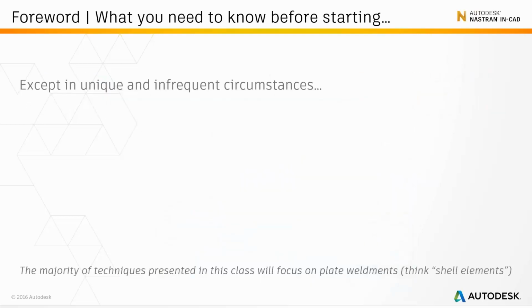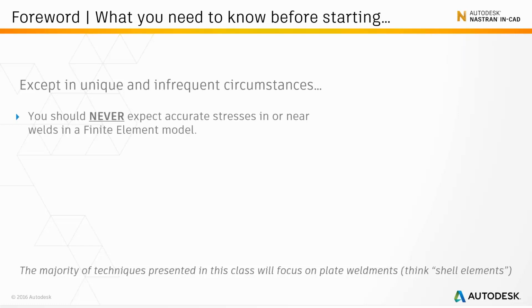So let's get into the content of today's webinar. Firstly, what do we need to know before we get started? Well, I need to stress that it's very unlikely that you will find that FEA stresses on welds will match that which are measured on an actual weld. What do we mean by this? If you were to run an analysis, come up with some results to show you stresses on your welds, if you were to then go and measure them, it's unlikely that you will find correlation or the exact number that you're looking for.